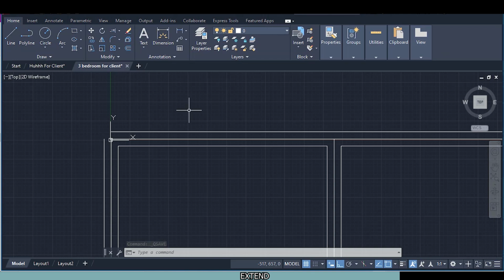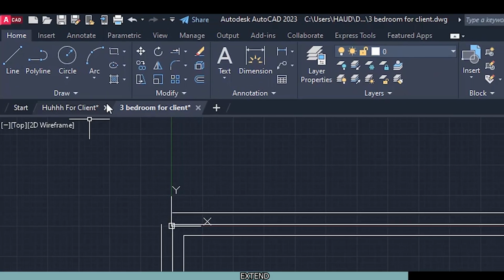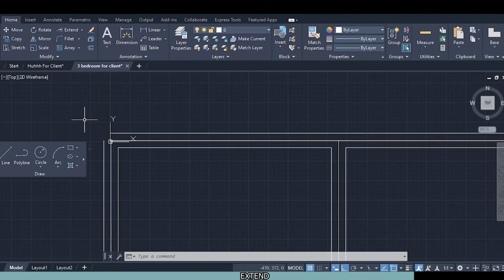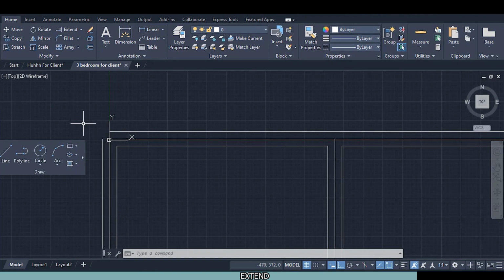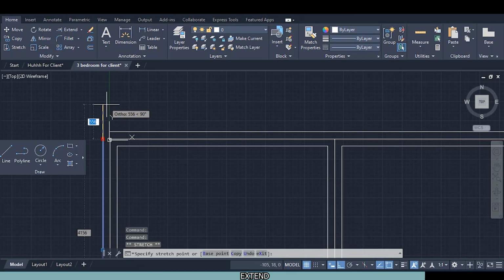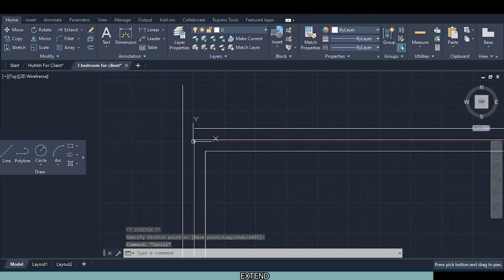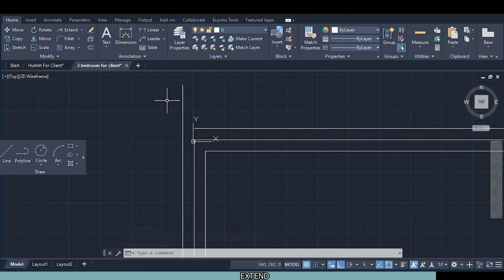I'm sure by now you're a little bit familiar with AutoCAD. These panels are all customizable. You can drag them in if you want. So let's work that way. If you just want to extend, you can click on this group, come up, press escape on the keyboard, zoom in a little, come this way, and we want our extend.